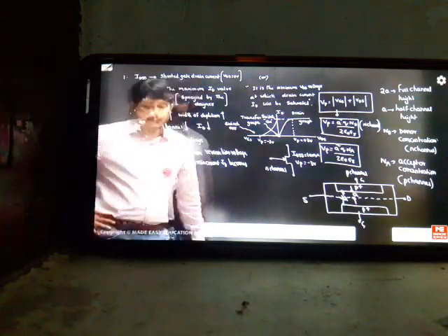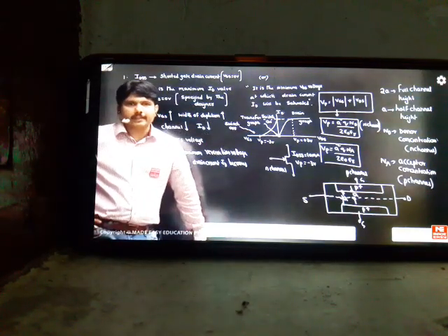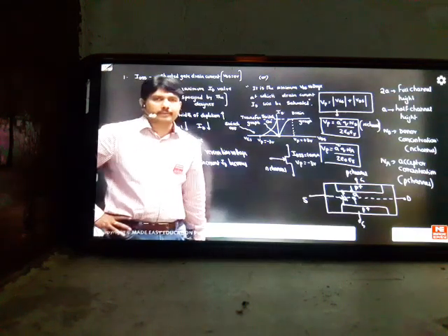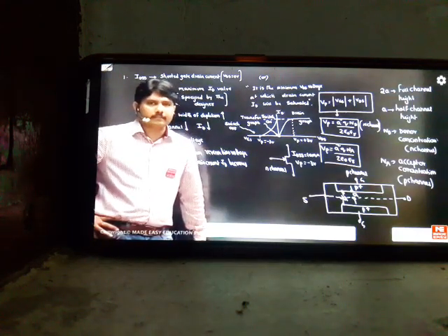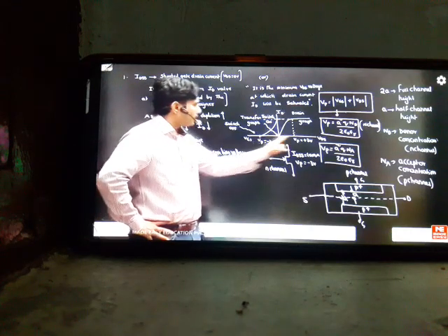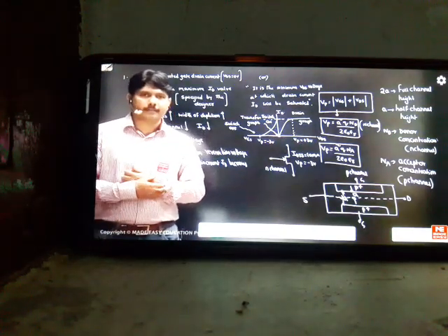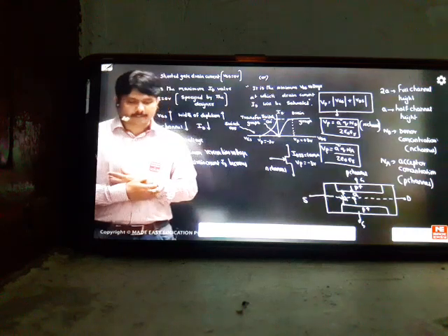Afterwards you can apply the signs. For VGS, the sign will be negative. For the VDS side, the pinch off voltage will be positive. Generally, we don't want the positive sign, we want the negative sign, because that decides where ID will be 0, which decides the pinch off technique. So that's why the negative side is more interesting, because this information will already be given by the examiner: at 3 volts, how much maximum current flows. So there is no importance of plus 3, there is importance of minus 3.